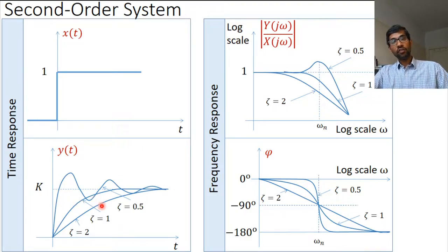But if the damping ratio is less than 1, you get some oscillatory behavior that we were talking about. The final value is this, but the output does not settle on its final value. It overshoots it, and then it undershoots it, and slowly these oscillations keep reducing till after a certain period of time the sensor settles down at its output value. The speed of these oscillations is given by the natural frequency of the system. That's how the damping ratio and the natural frequency work.